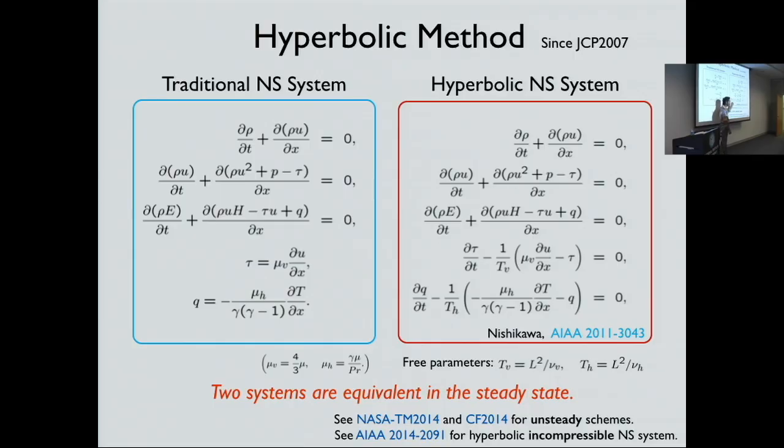The evolution equation for the viscous stress and heat flux. And this construction is based on this. The two systems are designed to be equivalent in the steady state. Or, if you simply drop the time derivatives, these two equations are exactly the same. Okay. So in this talk, I will focus on the steady problem to solve this to get a steady